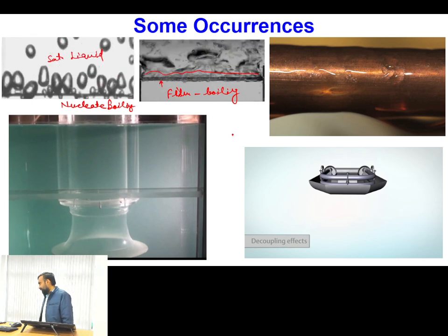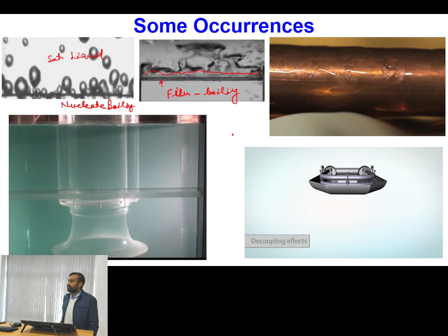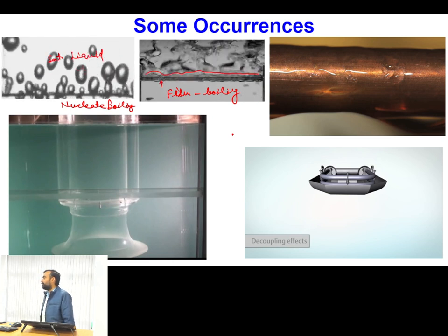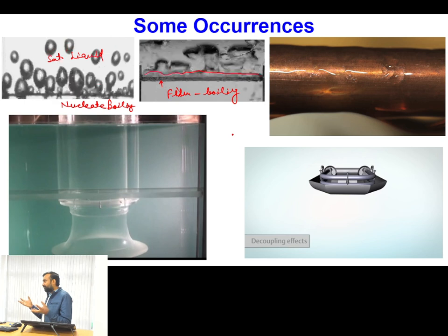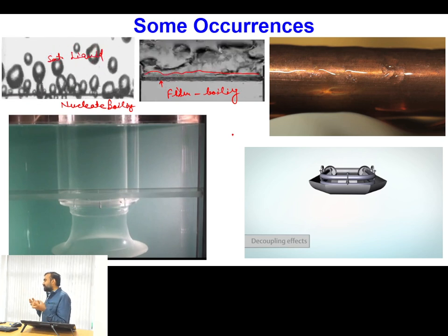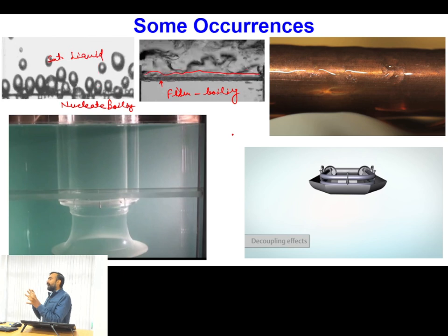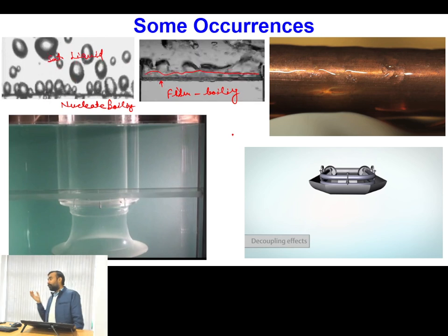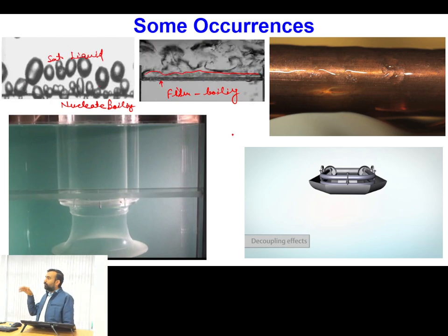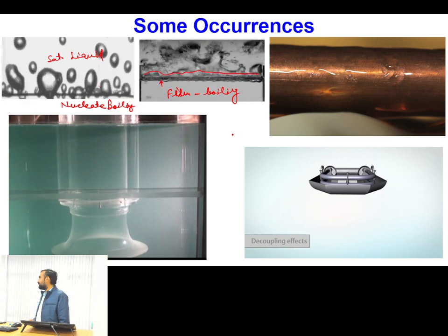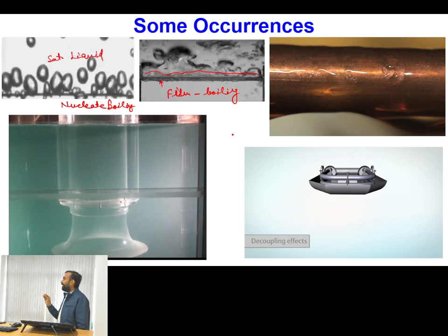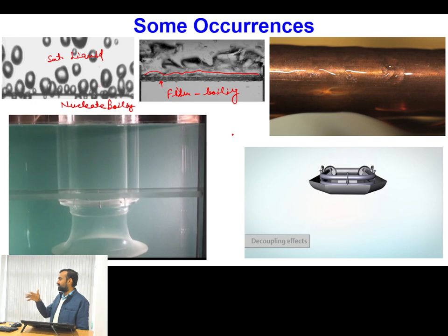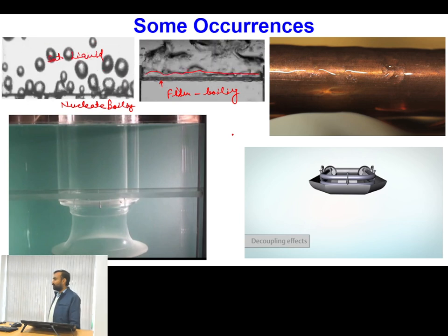But if you go to industry, particularly in process industry, wherever we have to form some products, what we have to do? We have to allow the different reactant liquids to flow continuously, because the plant will be operating round the clock, and moreover the different liquids which we want to react to form some useful product should have controlled flow rates, because we will be allowing them to flow at certain rates so that our reactions and final composition should be correct.